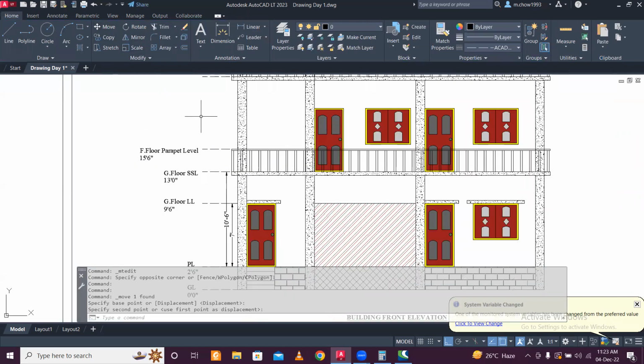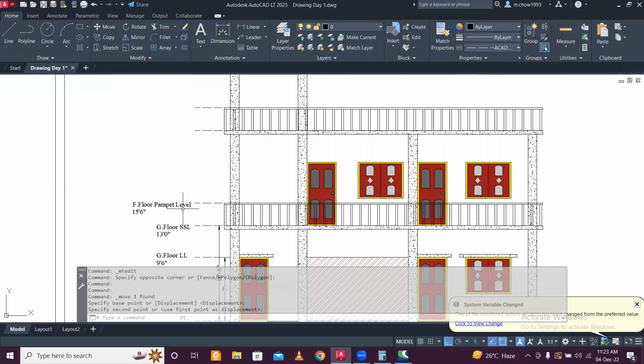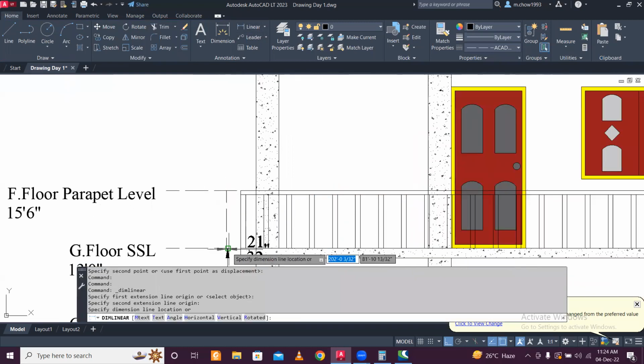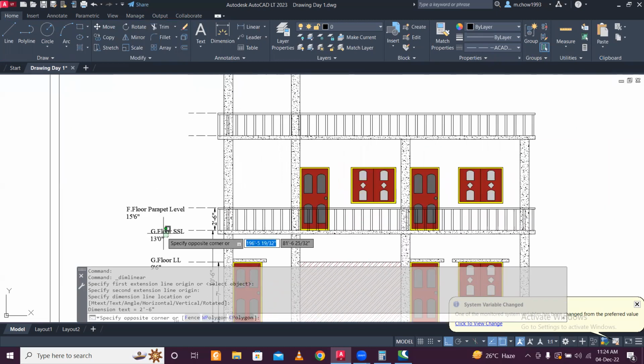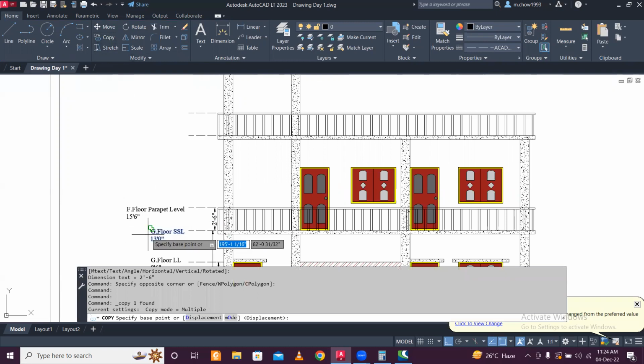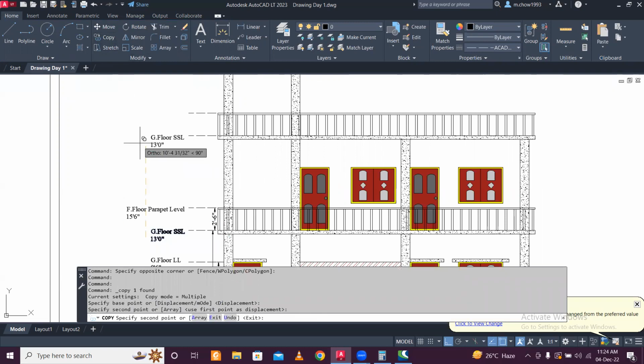So the parapet of the first floor. You can also mention it for clarity, always do this. Doing both things gives no problem. The next will obviously be the lintel level. You don't need to mention it, as you already mentioned it.